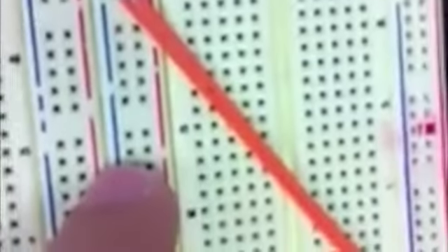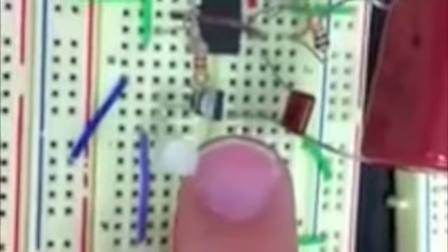And also, we have the output connected to a transistor to the base, powered by these 2 rails, which are again powered by the capacitor over here. And then the emitter goes through the LED, which then goes to this switch, which is connected to ground. So if we turn this switch on or off, it determines whether or not this red LED will be on or off. But anyways, so that is all the components of our electronics project.